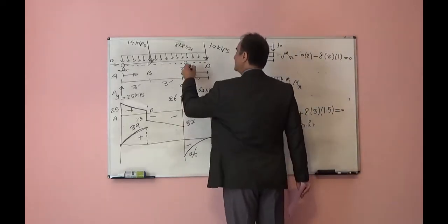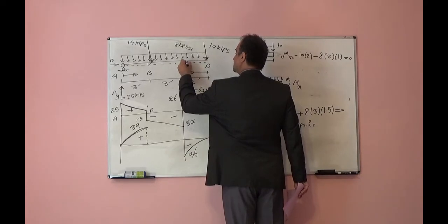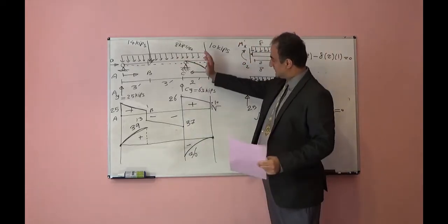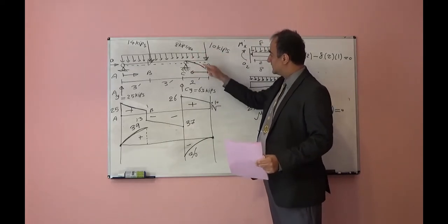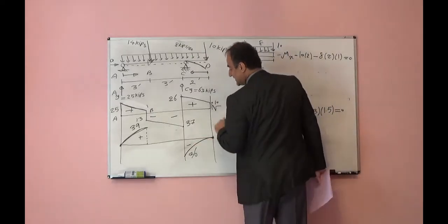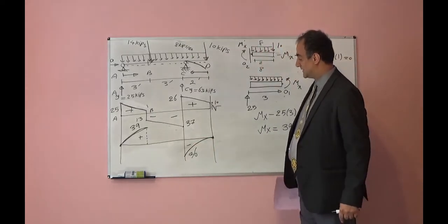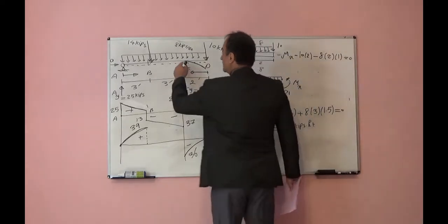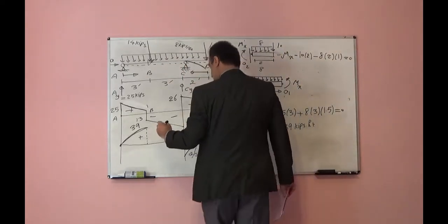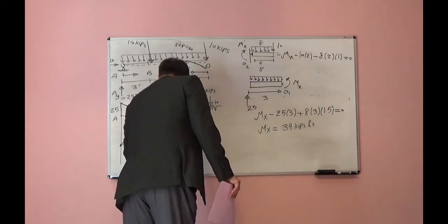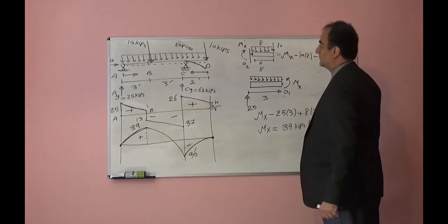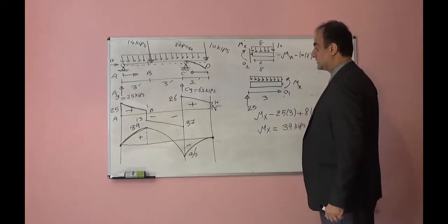On the other hand, how does this beam deform here? It will deform like this. If the beam deforms like this, underneath of the beam it is subjected to compression. So compression underneath of the beam means negative moment. From here to here, we know it should be a parabolic shape, so with one curve I can attach them together. This will be our moment diagram.